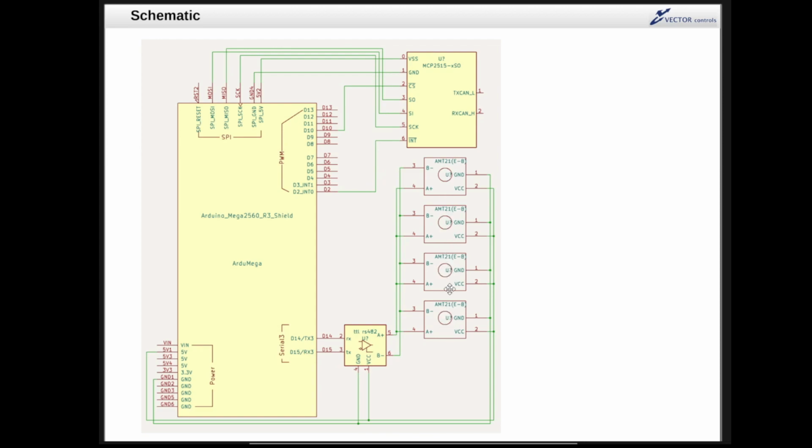The 4 sensors are placed on the bus and everything is powered from a single source. The Arduino will provide the 5 volts out to power the RS485 chip, the 4 sensors, and the MCP2515 CAN module. As we can see, it uses 5 volts and it uses SPI communication. The interrupt pin, if held low, will make the module write CAN, and if it's held high, it'll read from CAN.